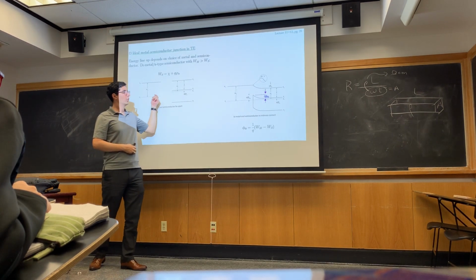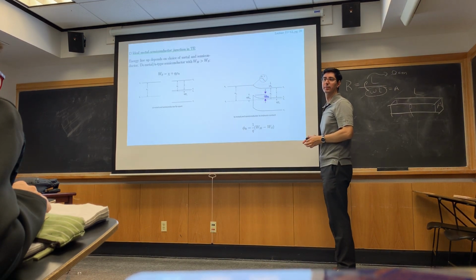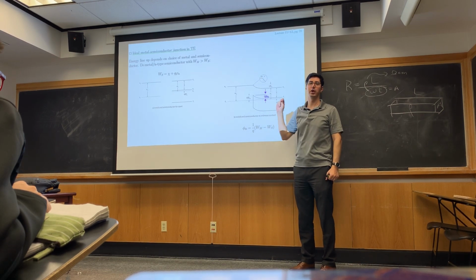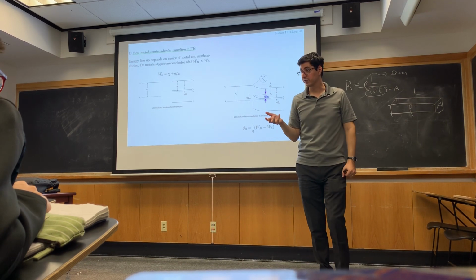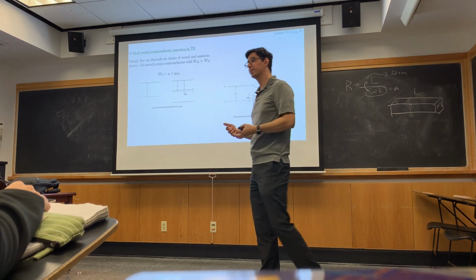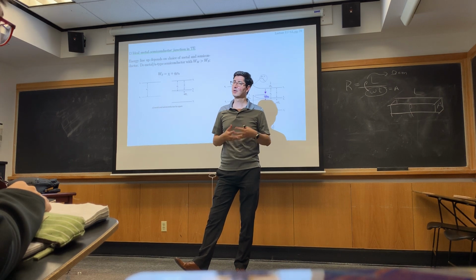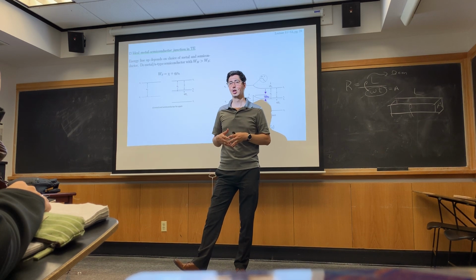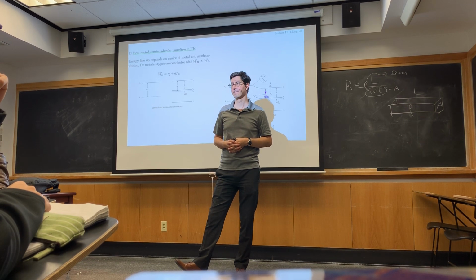Now, with the Fermi level, this is trying to show a zoomed in view right at this edge, and it's saying that there's very, very little potential drop on the metal side. You already know this, believe it or not, because when you solve the abrupt p-n junction, if it was an abrupt p plus n junction, you saw that there was very, very little potential drop on the p plus side. You can go back and look at that, and you can think about it, right?